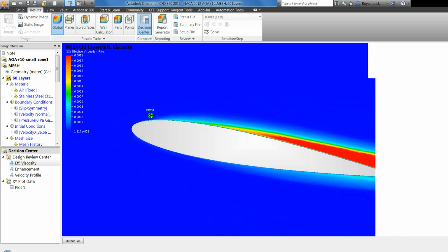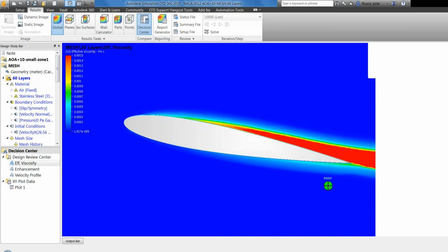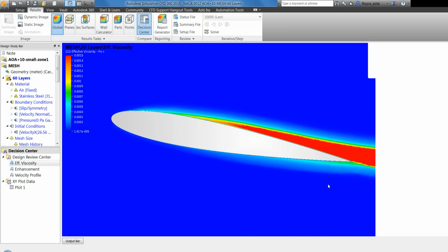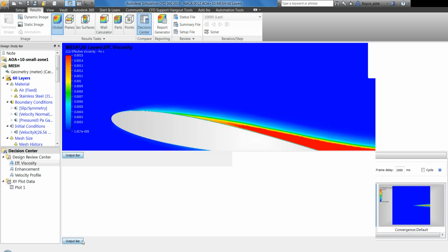Now, one thing to think about, there's a lot of things you can learn from this webinar. You can learn about, well, okay, what would it take to model external flow around some sort of shape? Okay, check. We sort of talked about that a lot. Another thing you can take away is that for heat exchangers, sometimes you need to think about convergence, and did you really allow your model to fully converge, especially if you're looking at the pressure drop of the system, because the thermal performance will converge fairly easily. You can start using what you learned about convergence criteria and doing a manual adjustment and really think about, when you look at the convergence plot, is it really done?